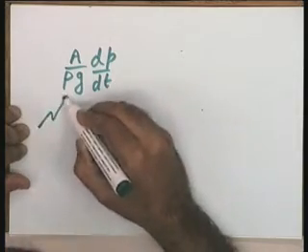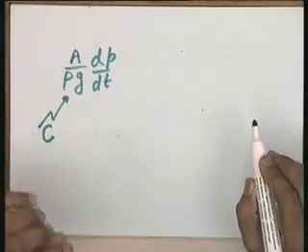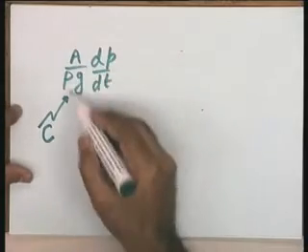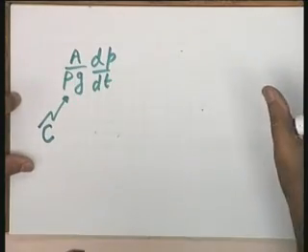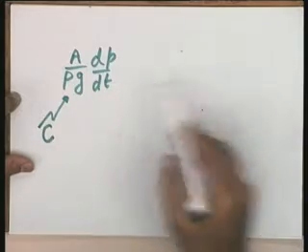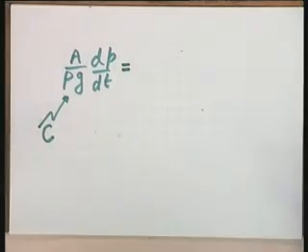Just to give you confidence, I am writing this, I think probably for the last time in these parameters, and then we will start writing directly in terms of hydraulic capacitance C. So it is C into dP by dt. Help me please, what is the flow rate situation?